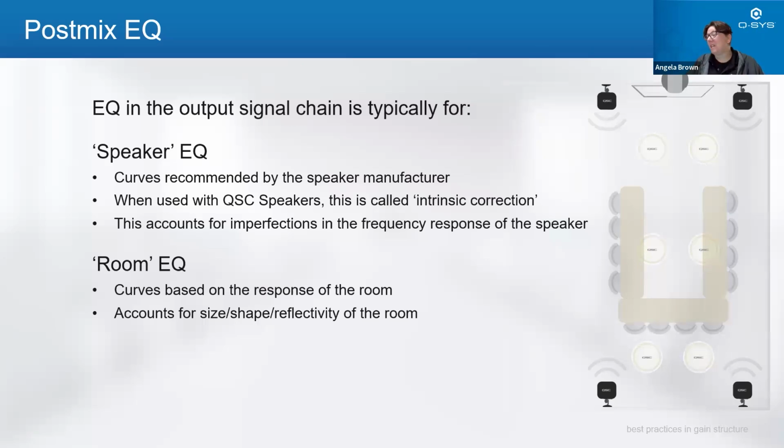The room is going to be probably your biggest battle. Conference rooms maybe not as big, but anything bigger than a conference room, anything with live reinforcement, and you really are going to need to take some time and make it sound good. Don't make it sound good for one microphone though. Make it sound good for the room and then make the microphone sound good, which is why I said earlier that I tend to do the room first, and then I start going through and getting my microphones EQ'd and set up.